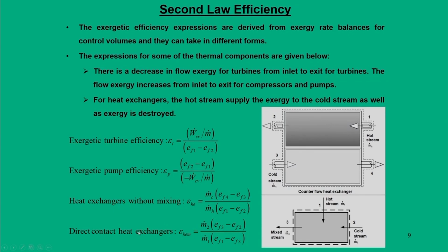When we use a direct contact exchanger, where the hot and cold fluids mix together and come out as a common stream, then the exergy calculation is a little bit different. We have to find the exergy for either the cold stream or the hot stream.